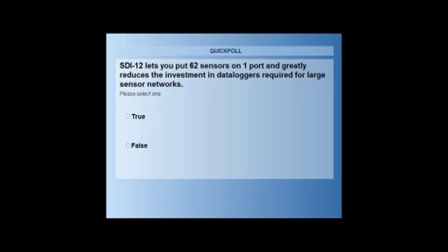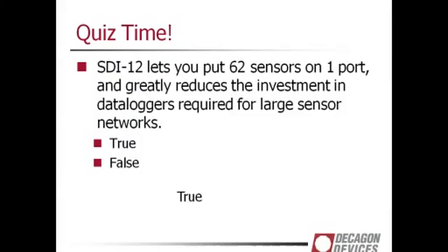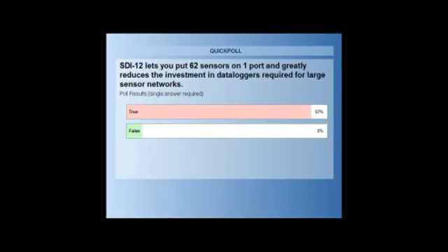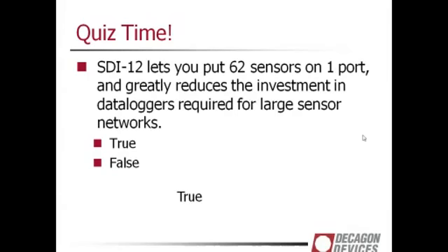100% true so far. Okay. The answer is true. This is the big advantage of SDI-12. It lets you put lots of sensors on one logger, and it reduces your investment in loggers.